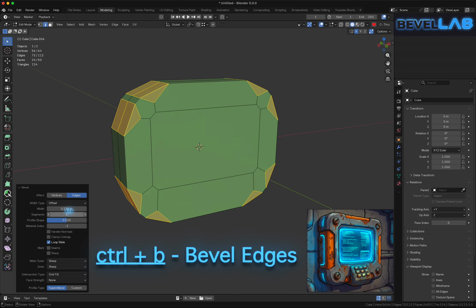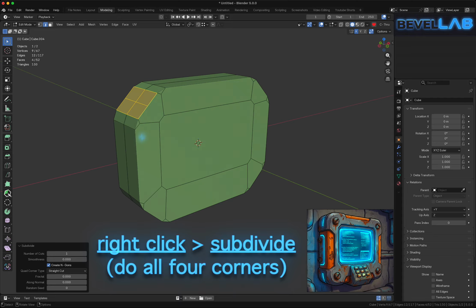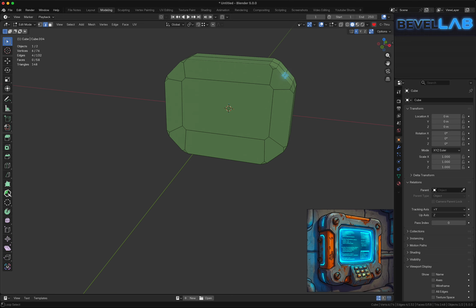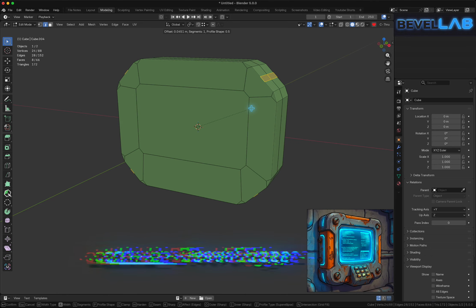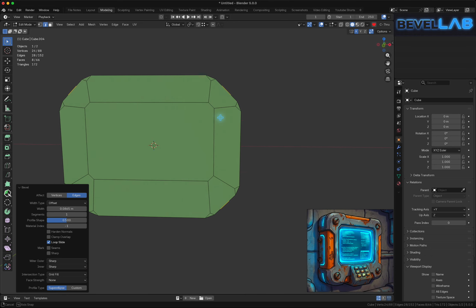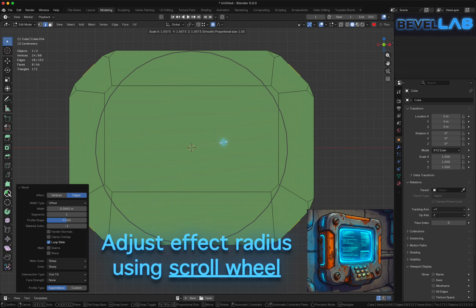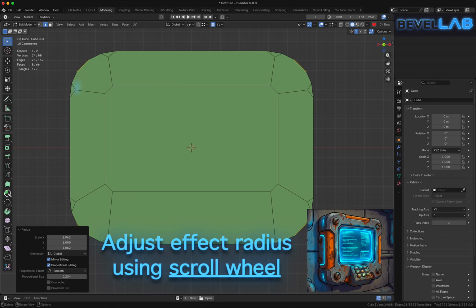I am doing this the hard way for a reason that you will see in just a moment. When we select edges and subdivide, we connect them with a new edge at each of their centers. Select those new edges now by holding Alt while you click them. Bevel these new edges. I could have just beveled this nice curve in one shot, but I wanted to show you another tool. Proportional Edit can help fix curved surfaces after you have messed them up, like humans tend to do. Make sure you prevent scaling in the Y-axis by clicking Shift-Y.